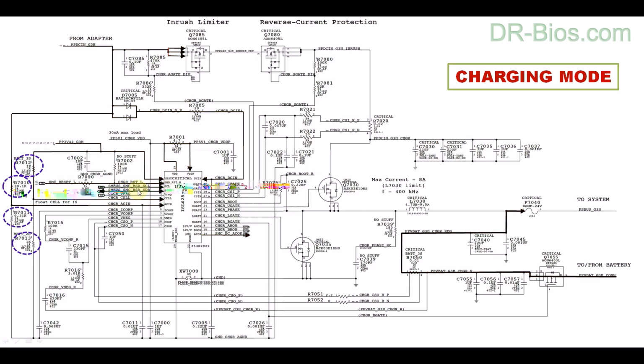An SMC which has been informed during a different process that the correct adapter is plugged into the device, informs charging IC through SMBus protocol that it's okay for adapter voltage to enter. And the charging IC drives two input primary MOSFETs one by one, delivers adapter voltage to back of the high MOSFET.